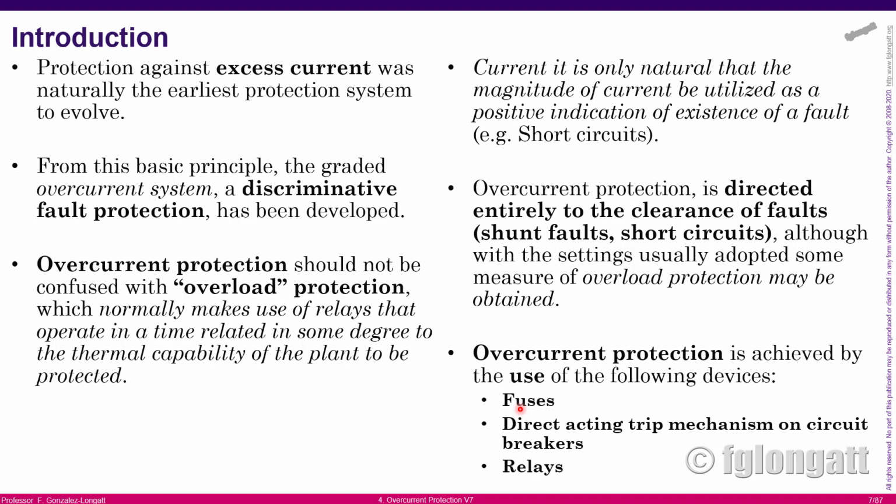The molded case circuit breakers that you can find inside your home have a direct acting trip mechanism included inside the circuit breaker. However, when you move to high voltages, the overcurrent discrimination must be outside the circuit breaker, and that is where relays start to be very, very important.